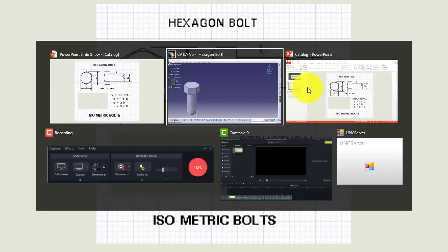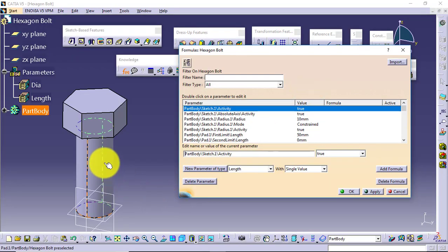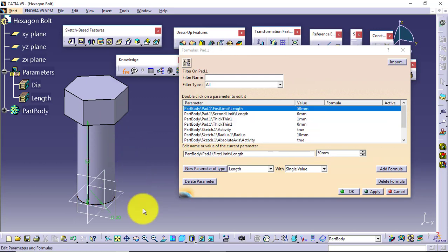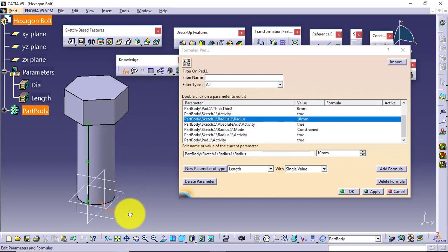So I will go to the software and I'll just click on the object like this. The software will show me the parameters over here. So this D20, that is diameter 20. If you select the parameter here, the same parameter will be selected here in the dialog box. So the software is actually considering it as radius. Remember that the software is considering it as radius, but we have defined that as diameter. So in that case you will need to give the radius value.